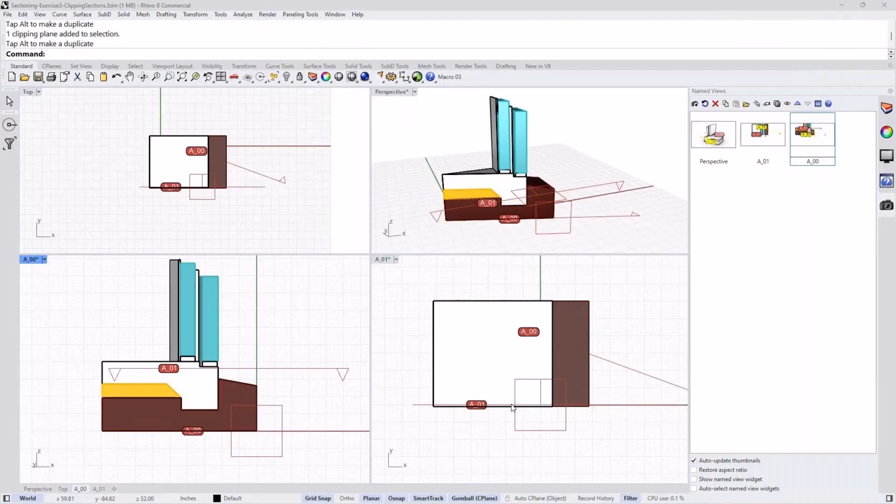Can we hide them from the viewports that they didn't cut anything? You can hide them from a modeling space altogether, or you can hide them not from specific views. I don't think you can either hide them or show them in modeling space, but you can hide them or show them in layout space, as we will see later. You can keep them on in modeling space, but turn them off in layout. But you cannot hide them from a specific view only.